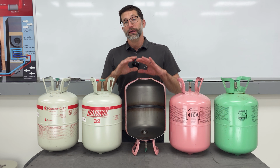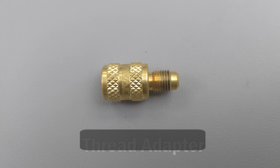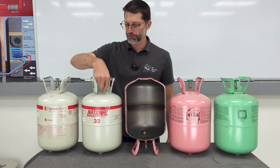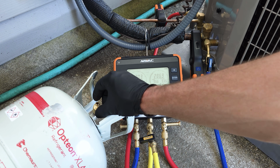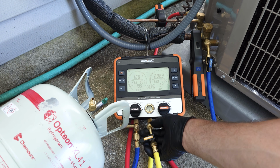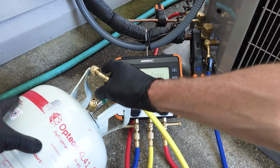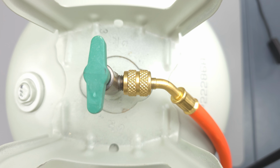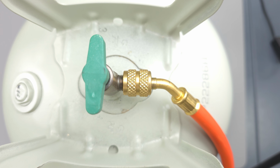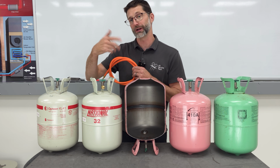Okay. The other thing is, with these left-hand threads, you're going to want a left-hand thread adapter. And so you'd use an adapter like this, because normal refrigerant hoses can't screw onto this. It's just a reminder that these are A2L refrigerants. That's the whole point of the red stripe and the left-hand threads. The other thing is, some manufacturers make a left-hand adapter on their hose, so it screws right onto the bottle without having to have an extra adapter on there.